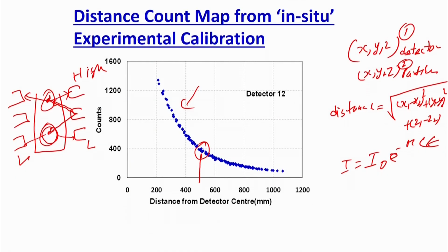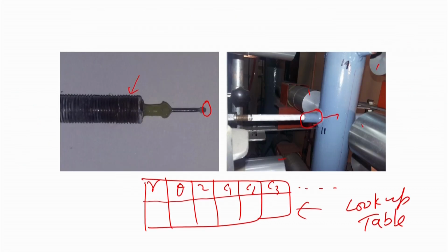So what we do is generate the photon count time series history, that is, how the photon count time series changes with the tracer particle location. So distance and location are the same: you move far, the distance increases; you come close, the distance reduces. But as I said, it is impossible to do experimental calibration for all the locations inside the reactor or inside the column of interest.